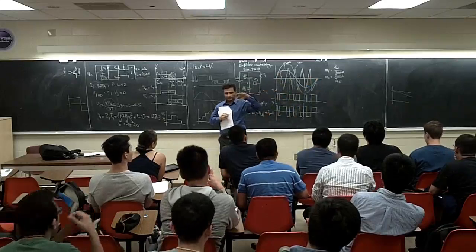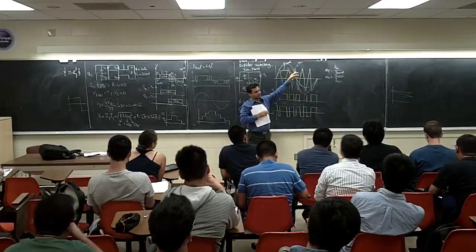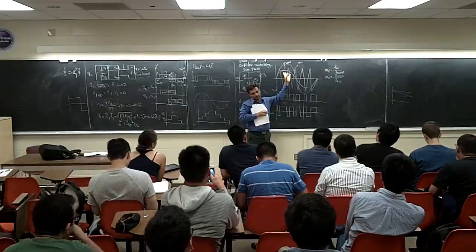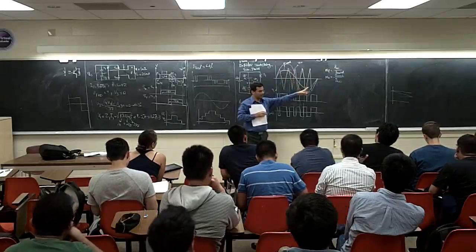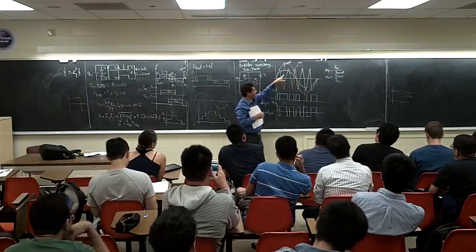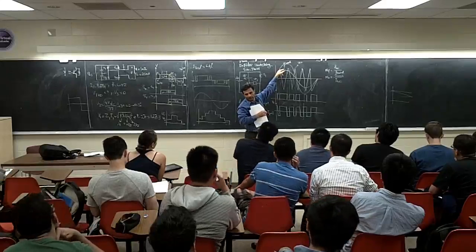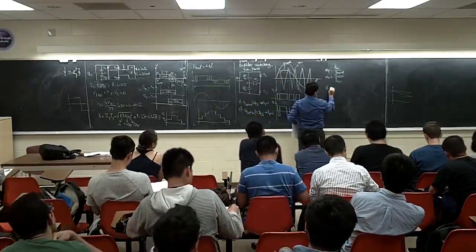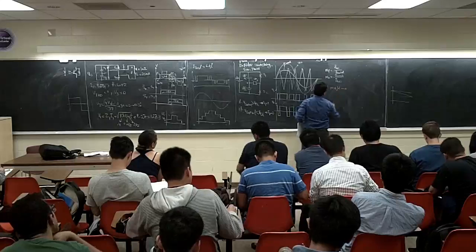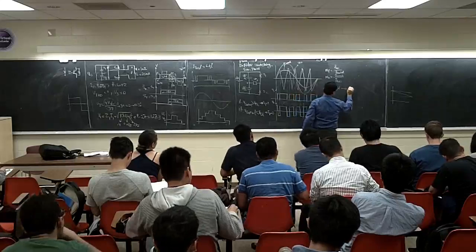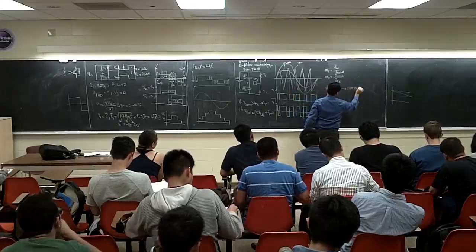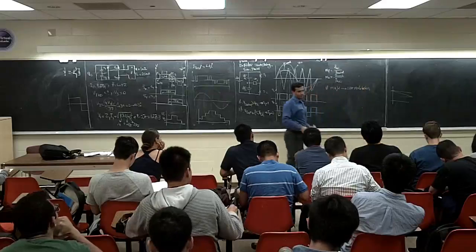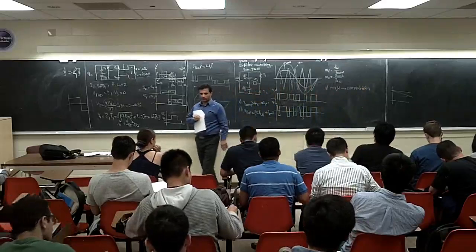What is going to happen? During this time, they're not going to cross each other, right? Because this one is much bigger than this one, right? They call this case up to MA is 1. 1 means both of them have the same maximum, and still they're going to cross each other, right? If MA is more than 1, they call it overmodulation. We'll talk about this one a little later more.